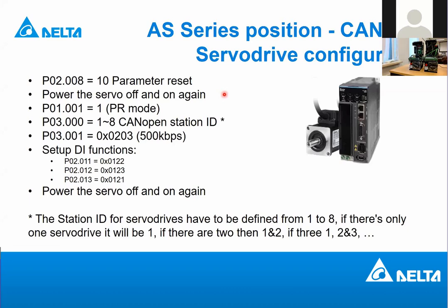As in our video, I remove the USB because my USB is supplying 5 volts. So you can see now the drive is off. Then I plug my USB in again. Let me power on the drive. Perfect. You can see that I've successfully reset the drive to factory default, and you can see that alarm 13 is triggered, alarm 013. So what is the next step?